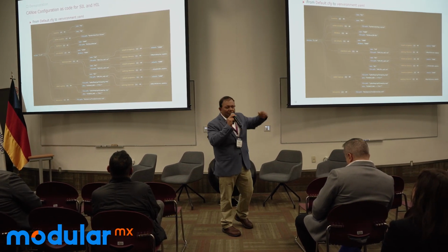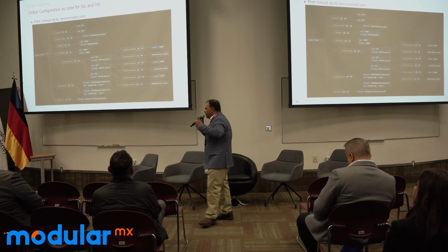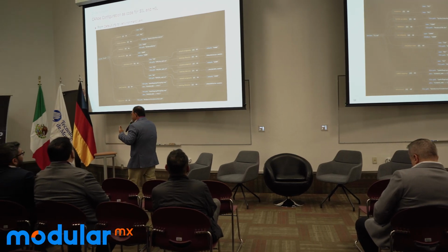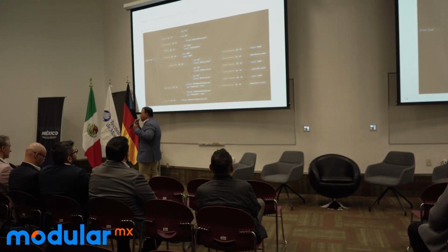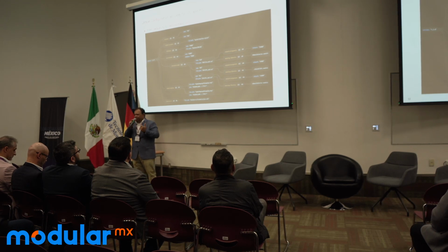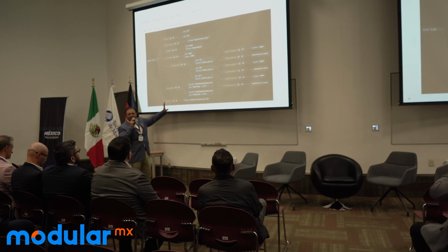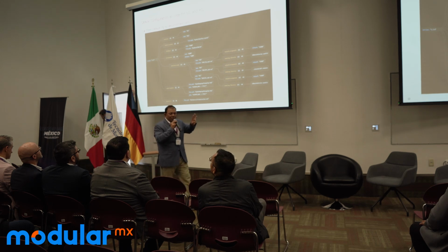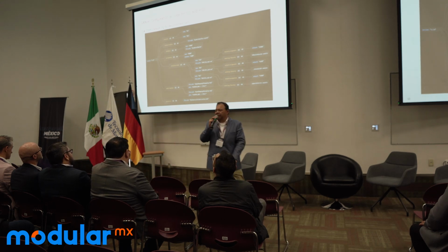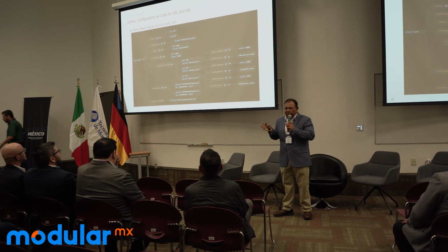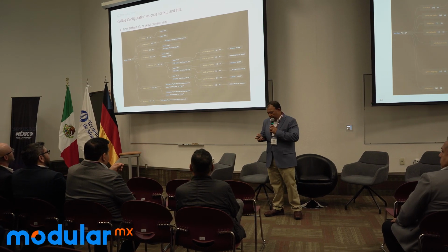But you can see where we have your XML files, different modules running, different DLLs, different simulation nodes, different ECUs inside the configuration, everything as code. This is a YAML file that we use to connect all the toolchain from Vector to do the automation.